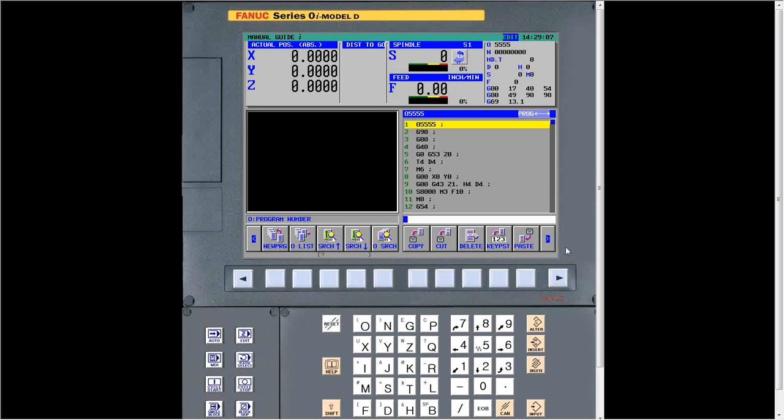Right, so that's engraving. But again, it's very simple. The main thing you've got to remember is to get the right tool type, either a drill or a ball nose end mill. That's the biggest mistake people make, is that they don't do that.